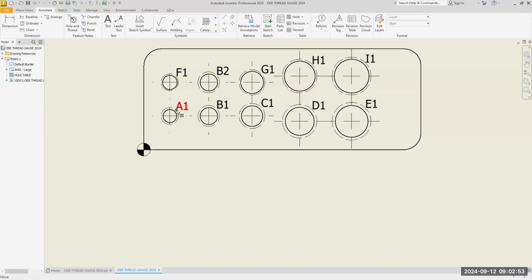If you hold your left mouse button down on that green dot, you can drag your part off. I would like for you to arrange yours like the way you see it on the drawing. You just move your cursor over the letter, hold down your left mouse button over the green dot, and do exactly what is shown here.